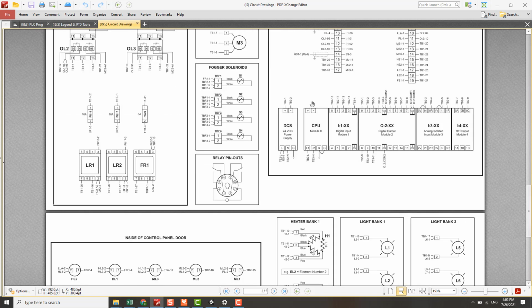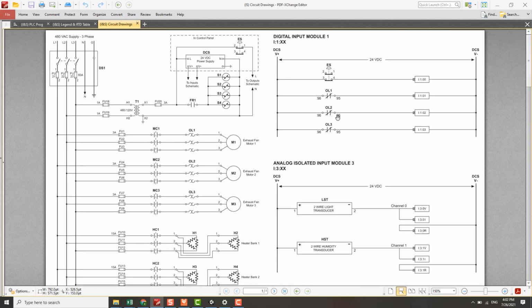So the DC voltage source, the external input switch or sensor, then sinks the PLC input load to the negative line via this common point. So the black probe is here, the common point is the negative side, then the red probe is here, channel 1. Input load 1, input module 1 channel 1.